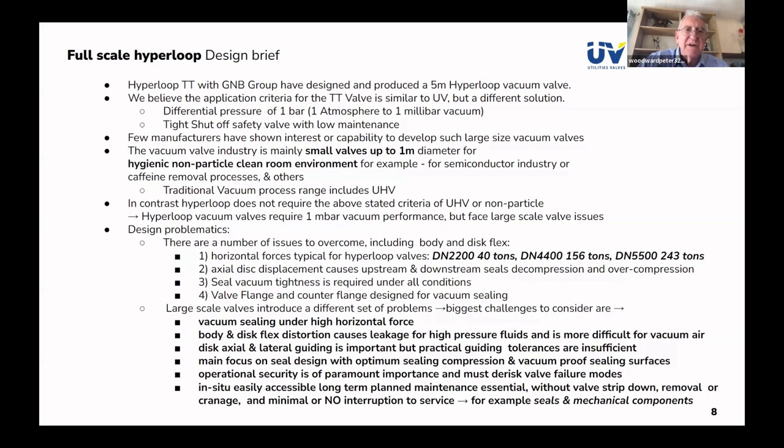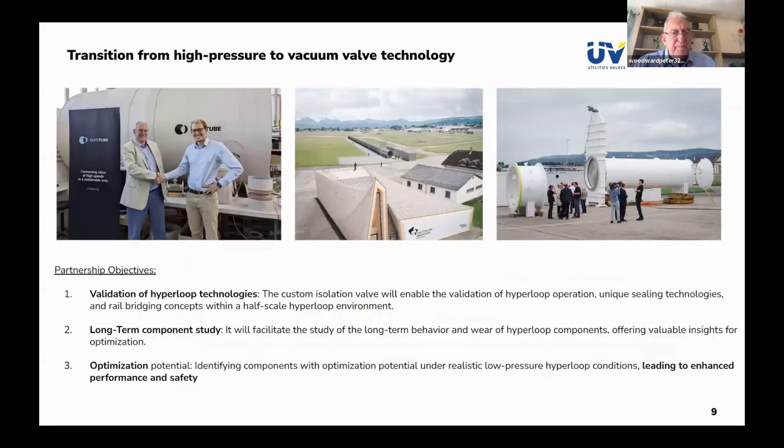And we've designed the seals in the valve in such a way that they are retained and can be broken down. The retaining rings are, for example, in segments of 4, which are easily lifted by one person, and you can dismantle the valve from the inside, replace the seal, and put it back into service in short time.